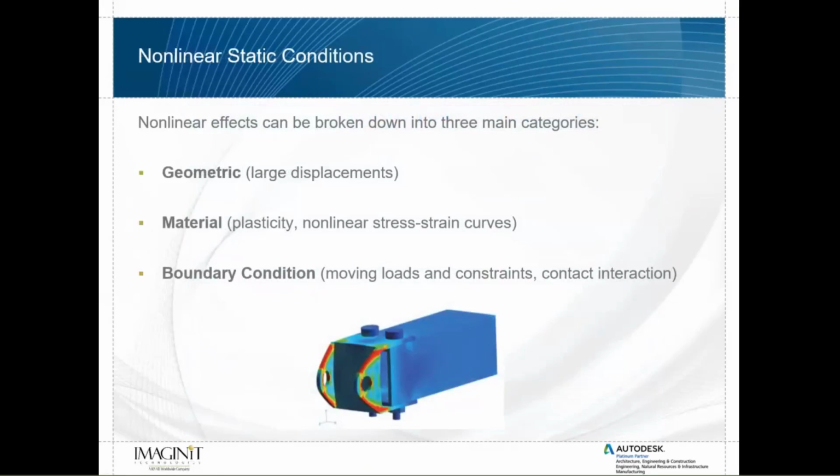All right, so let's jump into our nonlinear statics. A lot of times when people think nonlinear statics, the first thing they think about is nonlinear materials. So when you push your analysis to the point where you're loading your part and it's seeing a stress that goes beyond the yield strength of the material, you're going to be working in the nonlinear working range of the material at that point. And that's where linear static analysis starts to break down.